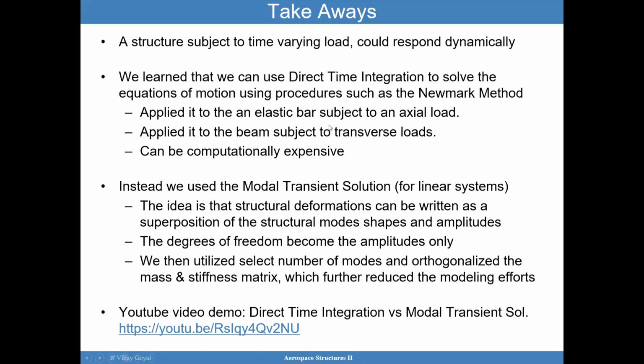that a structure can be subjected to a time varying load, and this structure could respond dynamically. We learned that we can use finite elements with a direct time integration procedure to solve the equations of motion using the Newmark method. We applied the procedure to an elastic bar subject to an axial load. We applied it to the beam subject to transverse load.